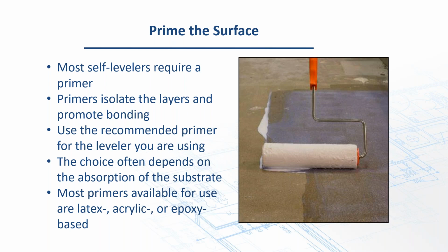Most levelers require a primer. They can be made without them, but they get very costly and they don't perform that great. When you're priming, it does a couple of things. It isolates the layers and promotes bonding, but more importantly, it kind of slicks out the surface too. So if you're using the proper primer, it will actually help the leveler flow. It slicks it out a bit.